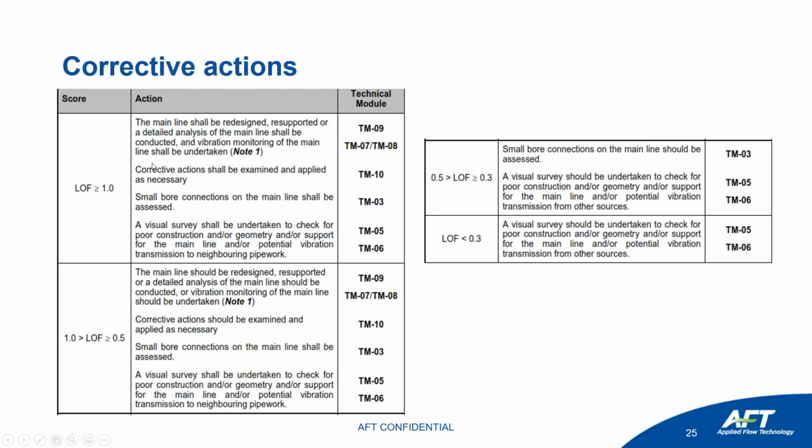For this LOF, the main line shall be redesigned, resupported, or a detailed analysis of the main line shall be conducted and vibration monitoring. So whenever the LOF is higher than basically 0.5, it tells you for flow-induced vibration, this can create a problem. So you need to take actions on that.